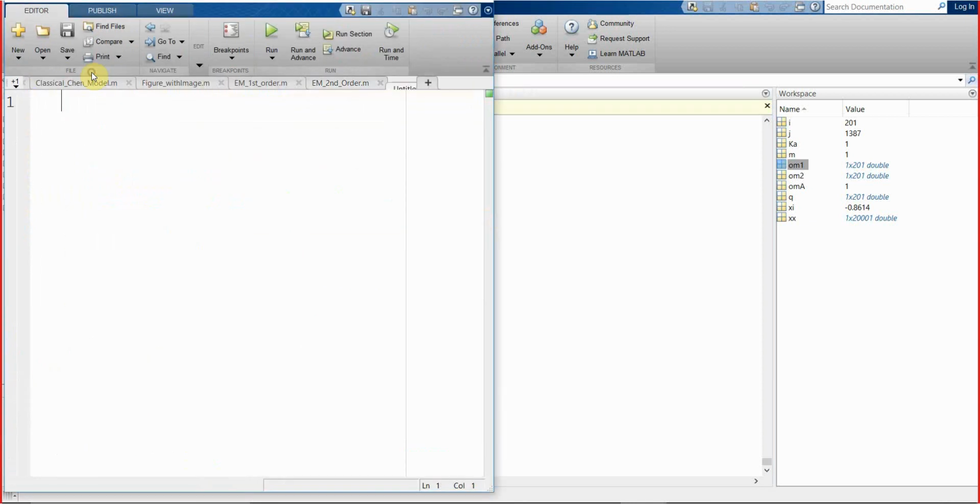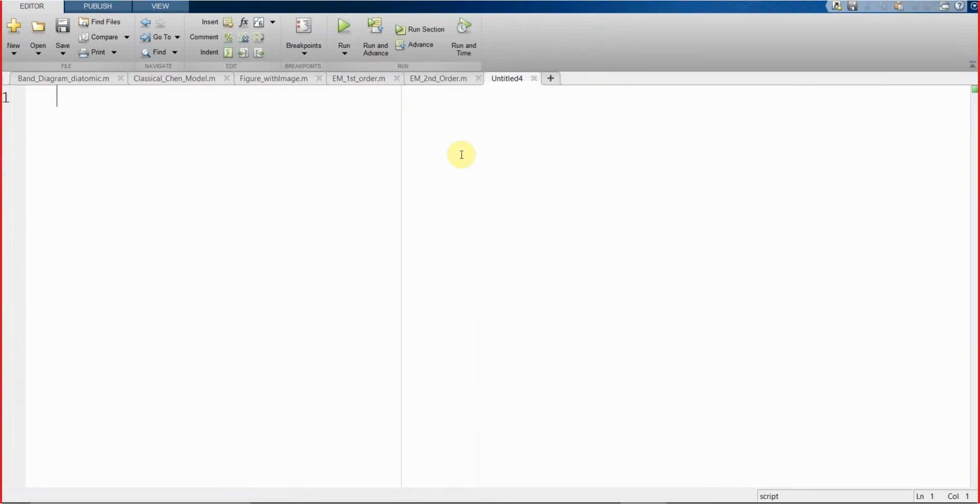This opens a new script file, and then you type some code here. But the code that you type here will not be run unless you press Run. If you press Run, you are asking MATLAB to perform all of the instructions that you give it through this window. This window is known as the script file or the editor file.